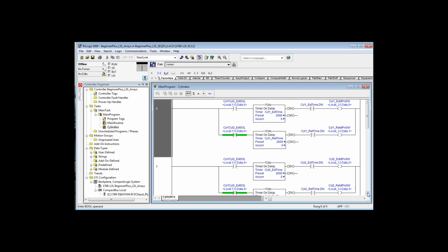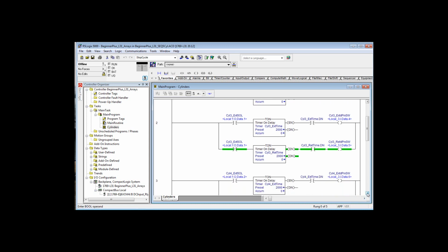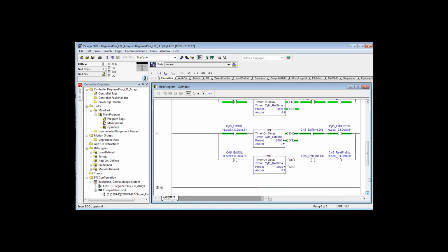That gave you 2 cylinders. Then you did the same thing again for cylinder 3, only this time you're using an output bit and it only controls this one cylinder, cylinder 3. Same thing for cylinder 4 and for cylinder 5. That was all that you did, was duplicate logic that you already understood. So now you have 5 virtual cylinders.